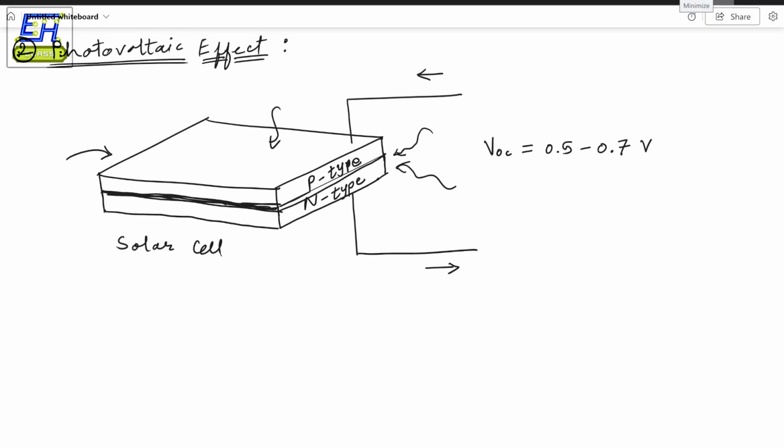This is a very complex topic in itself, and there is an entire research branch focusing on increasing the efficiency of solar cells. Another trick that you can use is to have some kind of reflective layer behind the bottom layer, so that some of the light that goes beyond the junction can be reflected back, and some small portion of it can be absorbed.